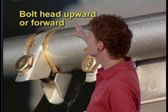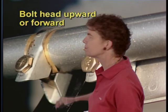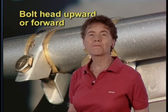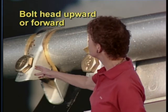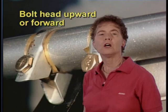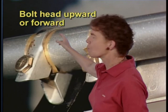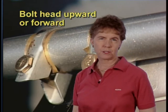Now, unless it's already specified or required, the way you install aircraft bolts is so that the bolt head is upward or in the forward direction. That way, if the nut comes off, you still have a pretty good chance that the bolt is going to stay in position. So the bolt head should be upward or in the forward as opposed to a rearward position.